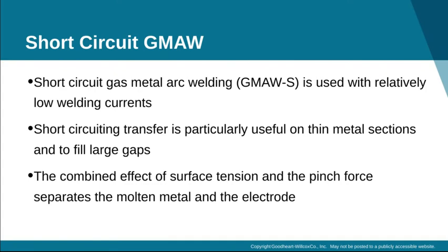So if you do any sheet metal welding, it's probably going to be MIG or TIG. For example, on the welding certification tests we do, you'll have a 1/8 inch gap. It's kind of a large gap when it comes to welding.